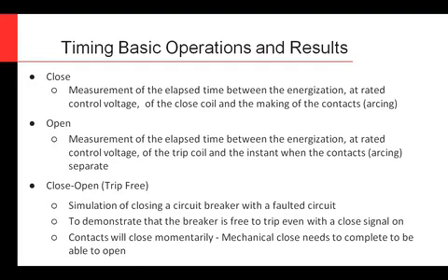Something else you'll see is the close-open, referred to occasionally as trip free. You'll hear dwell time. This is a real world condition where the breaker closes in, sees a fault, and trips back out immediately to clear it. What we measure here is when you close the breaker, as soon as that first metal-on-metal contact touches, that's your time 0. Then you keep recording, and the breaker might not even come all the way closed. It'll come back open, and as soon as the contacts separate again, that's your other time, and the difference between them is your close-open time, or your dwell time. These are the most common measurements performed.